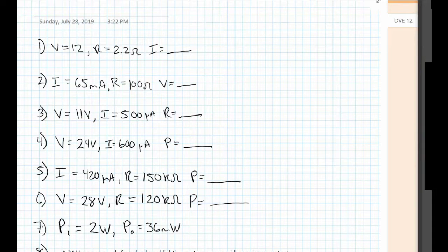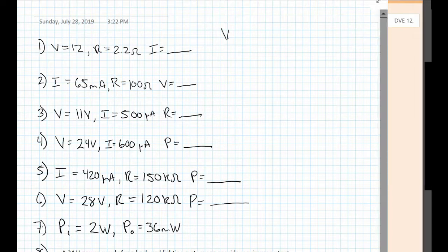Okay, so I picked out some problems from one of my old textbooks, and we're going to take a look at that now. We should know how to do all these. We just went through the demonstration. So let's get started. Actually, let's look back. What are we looking for? We're looking for current. So current is equal to voltage over the resistance, 2.2 ohms. So there, calculator, 12 divided by 2.2, so 5.45 amps. All right, so right there, 5.45 amps.